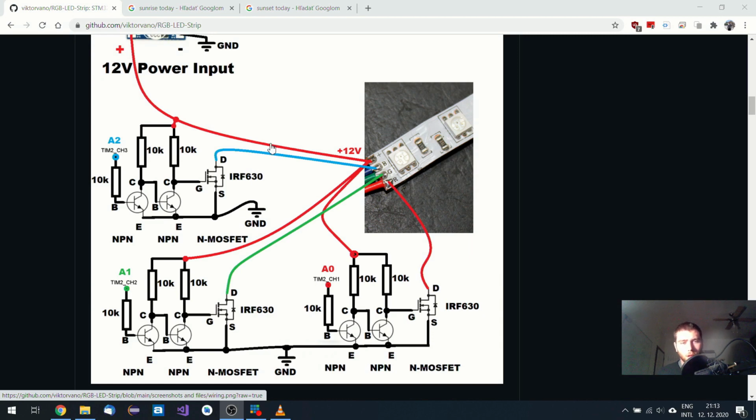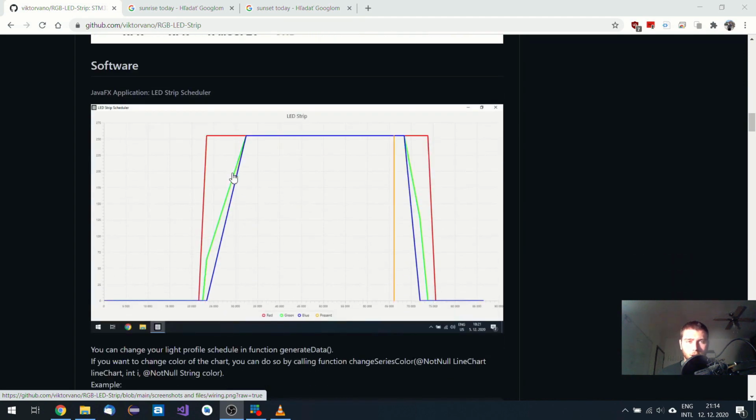Also I can mention that this PWM frequency cannot be very high, because these MOSFETs have quite high capacity between gate and source. So with this resistor it creates some sort of low pass filter. That's why I decided to run this at 1 kilohertz, because it cannot handle too high frequencies, and 1 kilohertz is quite smooth for your eye. You won't notice any flickering. But if you run this PWM frequency at about several dozens of hertz, you could notice some flickering. So that's basically it.